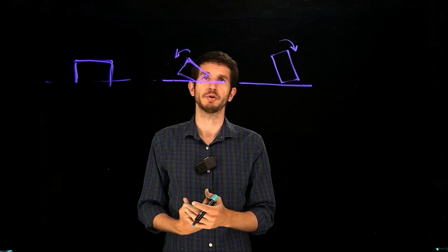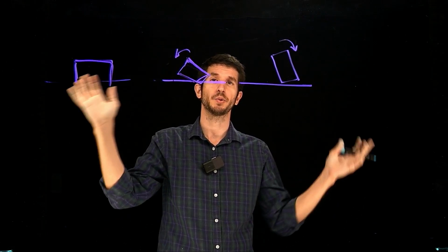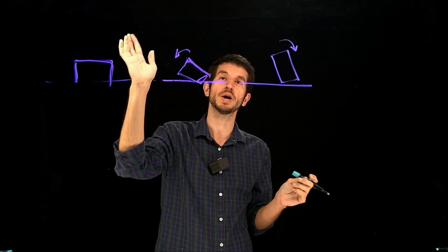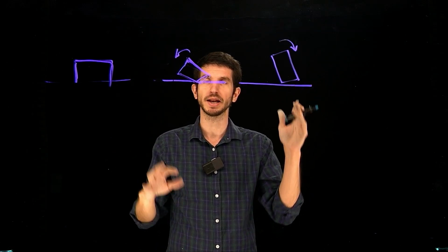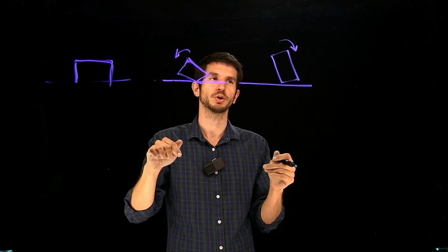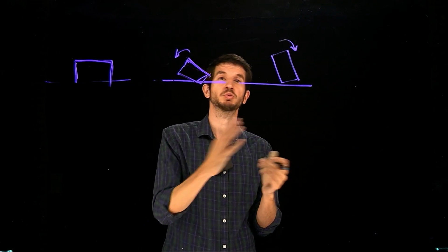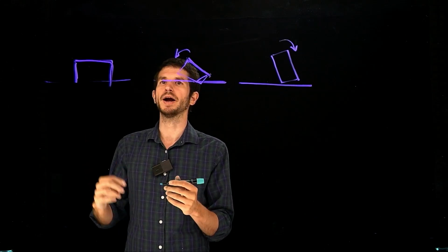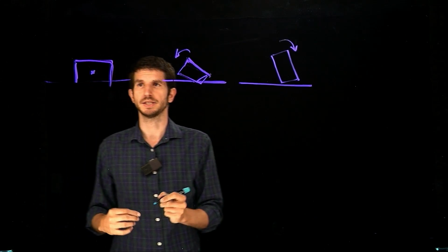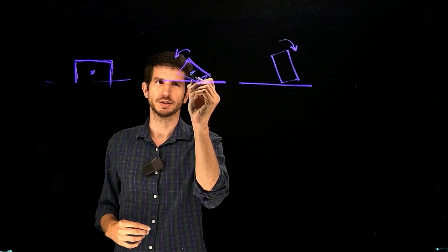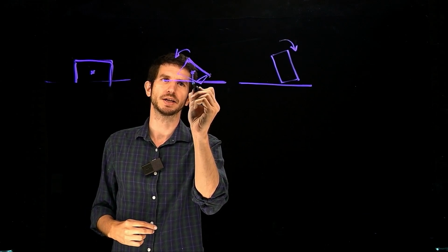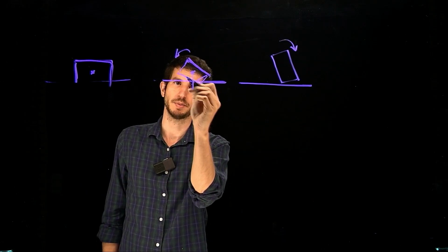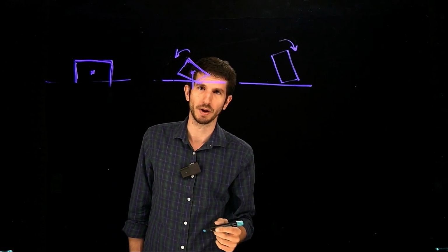Of course, the rotation is going to be a result of a torque, because once we stop pushing, then we're going to have breaking of the balance. When I'm pushing, this is an equilibrium, zero torque. Once I release that, forces get out of balance, and net torque appears. The torque is going to make this thing rotate, okay? And the question is, which one is going to be the direction? That is given by the criteria of stability. It says, find the center of mass of an object, and if I project it directly vertically down, if that falls within the base, then it will go back to that position.